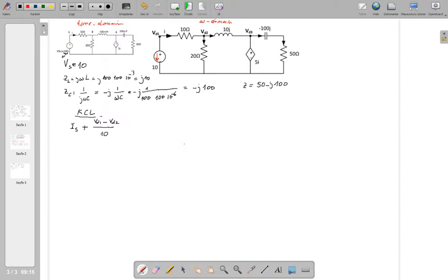So let me remind you what node voltage is. Node voltage is the voltage between a node and the ground. So ground, assumed here, is this. So when I say node voltage VD1, it is the voltage between those two, so you can easily say that voltage is the same as this. But if you write this element's voltage, it is not just one node voltage that you're going to use. It is the difference of those two node voltages. So there are two elements connected to that node, therefore there are two terms in the first equation here.